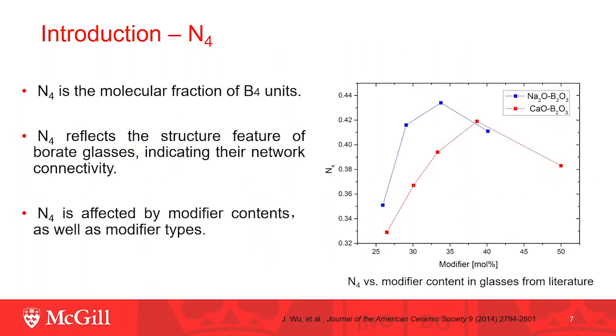N4 is the molecular fraction of B4 unit. It is an important parameter to reflect the structural feature of borate glasses, indicating their network connectivity. From the literature, we can say that with initial modifier addition, N4 increases with increasing modifier content due to the conversion of B3 unit to B4 unit.